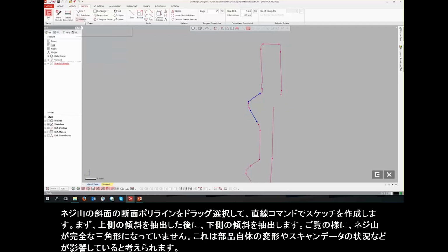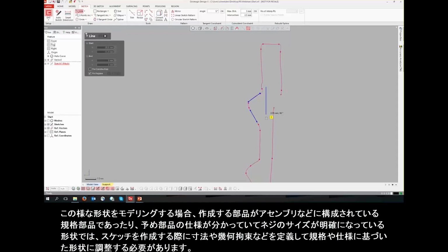If we were interested in generating a standardized thread or another accepted thing that goes into an assembly, or we always know that the company that makes this part always uses the same thread size, we can construct sketch geometry here to further constrain these shapes to be ideal, right? So we'll go in here and make a triangle real quick.